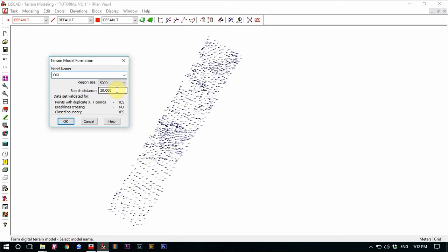In my case here it is maybe around 120 or 110. They are not on a uniform distance because it's raw data as the survey was done and I downloaded it from the instrument. So roughly my points are around 100 to 120, but I am giving here 150.